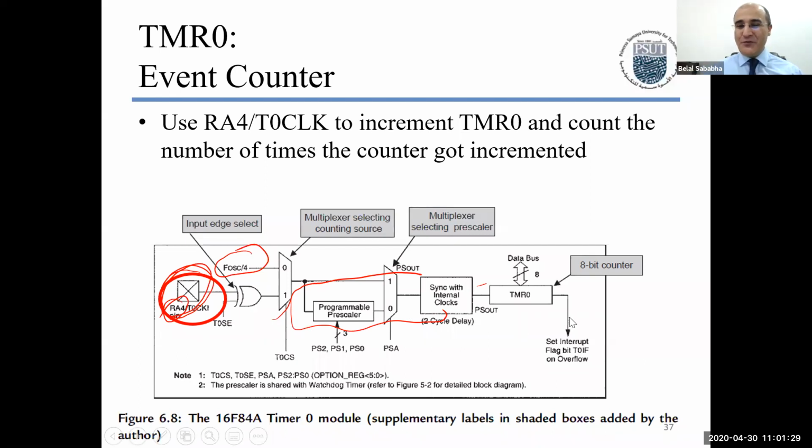Imagine what this can do. This can cause timer 0 to increment without writing any piece of code to watch for anything. This could be tied to a door. It could be tied to anything.